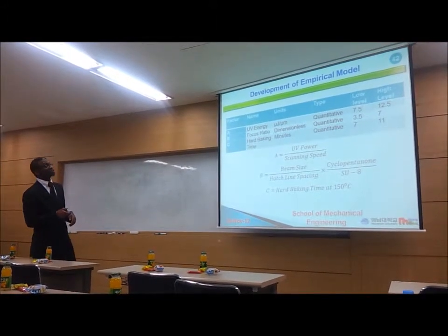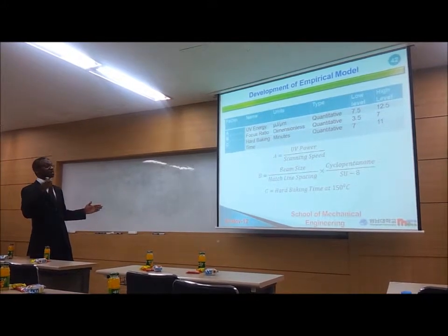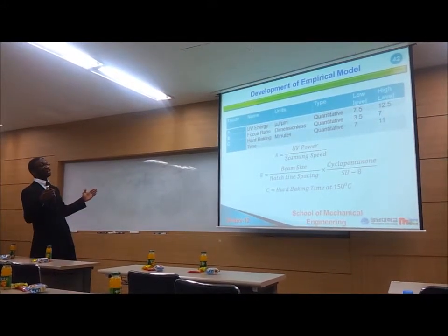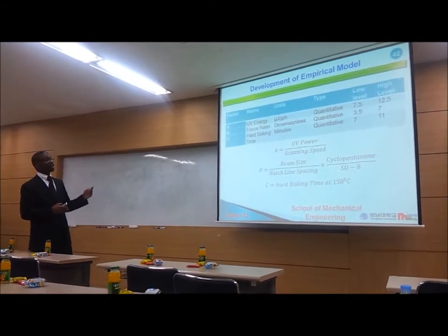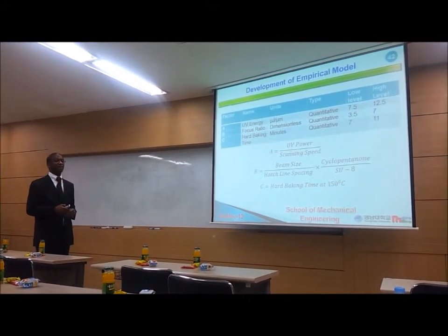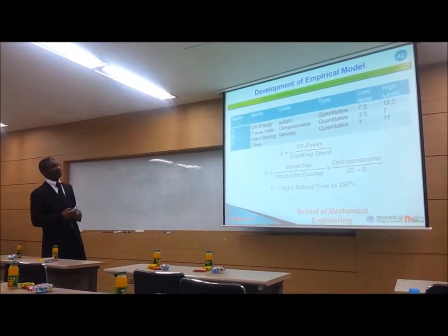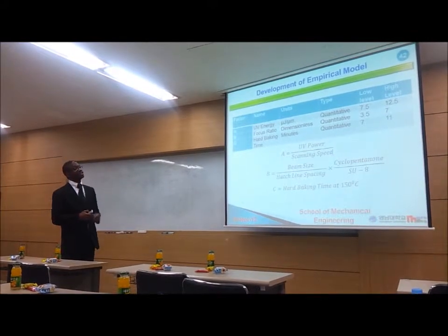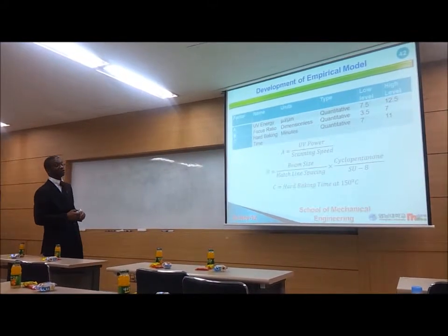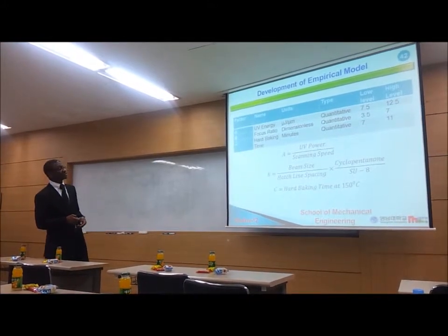But here I had to set the levels, the minimum and the maximum, because if we don't have any range, we have a high risk of not getting a mask. For example, I was using a power of less than 20 micro, and it was very hard for me to fabricate a mask. But when I changed my power to around 150, it improved fabrication of the photoresist mask a lot.